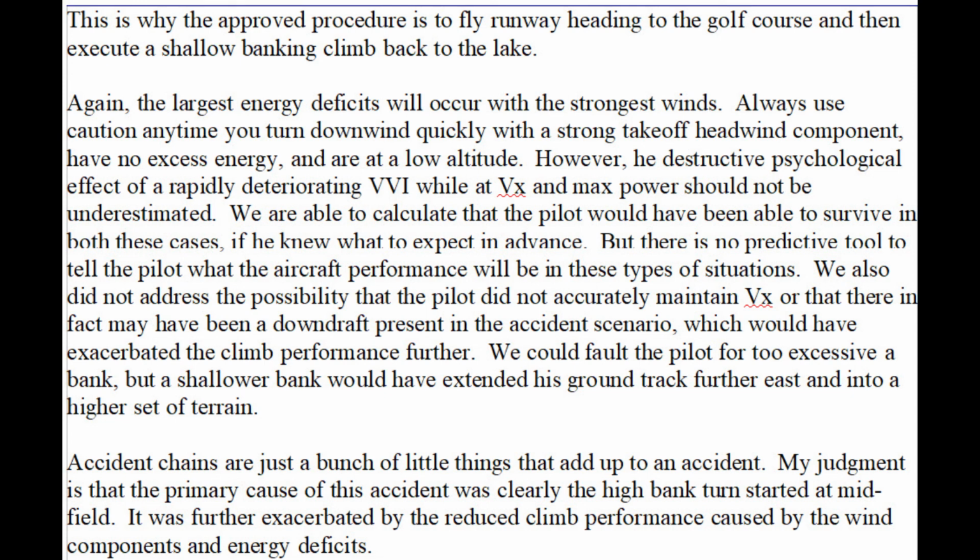Accident chains are just a bunch of little things that add up to an accident. My judgment is the primary cause of this accident was clearly the high bank turn started at midfield. It was further exacerbated by the reduced climb performance caused by the wind components and energy deficits.